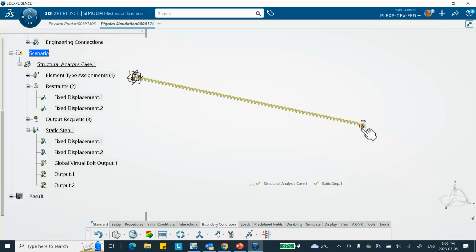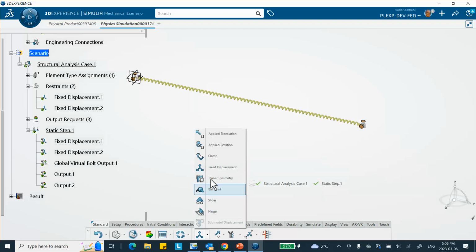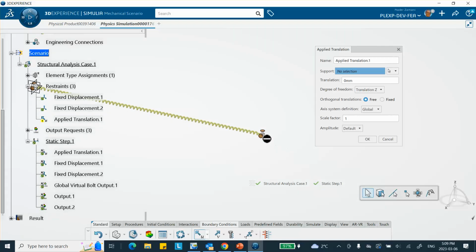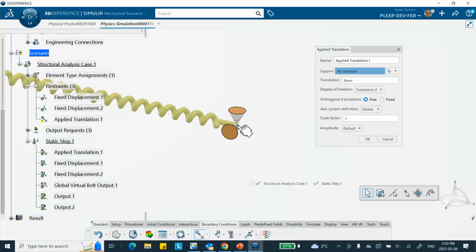So right now, we're in the first step. So you go here, under apply translation, you select that point. If you're having a hard time picking it, zoom in there. In the direction Y, by the amount 0.1 meters, which is 100 millimeters, because the unit here is millimeter. Or you can type 0.1 meter, it's going to convert it, unless you go and change the units in your menu. Okay, that's pretty much it.